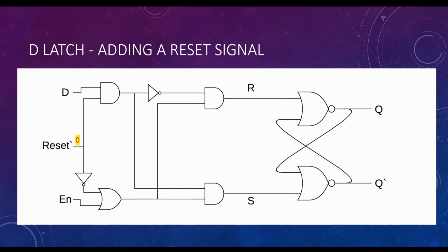So whenever reset is active, and it's active low on 0, that's what you get. You get a 0 on the AND gate, and therefore the output of that gate is 0, and you get a 1 on the OR gate, and therefore the latch is enabled, and therefore it is being reset. Now, that might not be how they do it in the real world, but this is something that can work. I did see other implementations, but the idea here is valid.